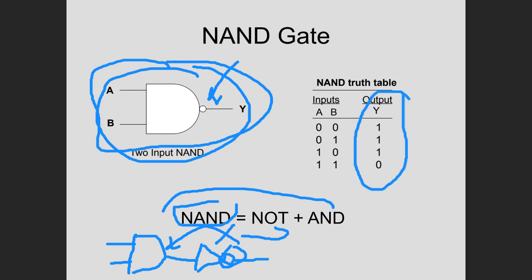That was right here. So it was a 1, and all the other inputs were 0. The output column for the AND was 0, 0, 0, 1. That's what you have up to this point. But once that hits the state indicator, all those bits are inverted. If you compare this table to the output truth table for the AND, you'll see this is the exact opposite. So basically, the NAND gate takes the AND gate and inverts it. The language we'll use is that it NOTs it.